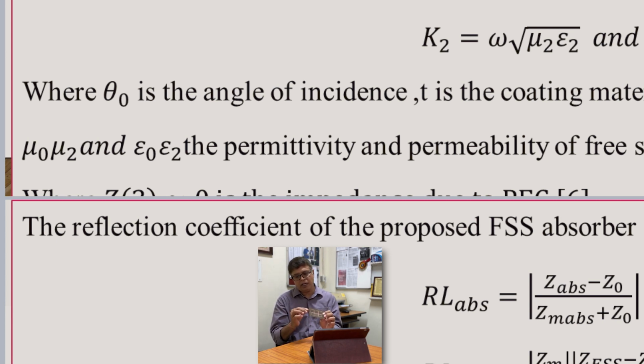Now if we see the center part, this is FR4. The permittivity of this FR4 is 4.7. Now if we see the back side of the RF absorber, this is the ground plane. So in total, what we can see is the S11 of the complete structure. If it is perfectly matched, the S11 must be minimum, or minus 10 dB, resonant at two different frequencies: one at 2.4 gigahertz, another at 1.6 gigahertz.